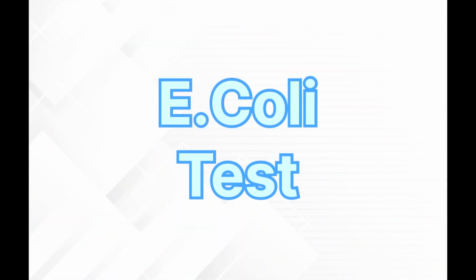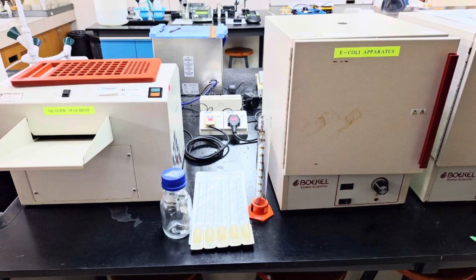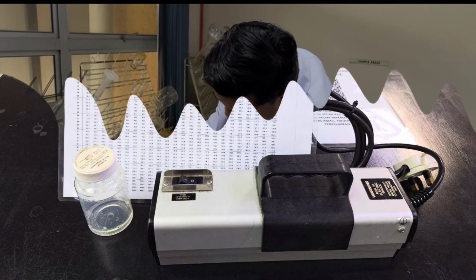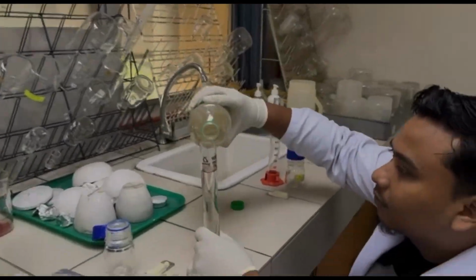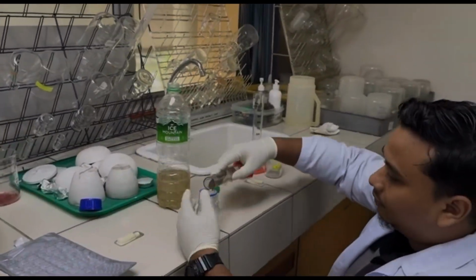The next experiment is about E. coli. The apparatus for E. coli is a standard coliform sample, E. coli sample tray, Colilert, sealer mold, sealer machine, and E. coli apparatus, glass jar, next is a UV light and E. coli MPN table. First, we need to measure 110 ml of each sample using a measuring cylinder. The sample was poured into a glass jar.